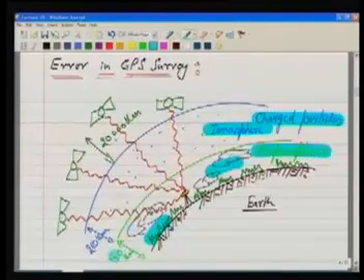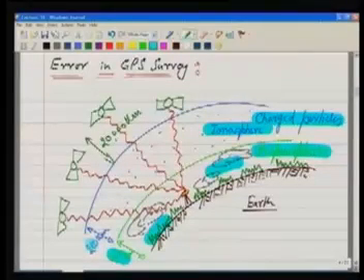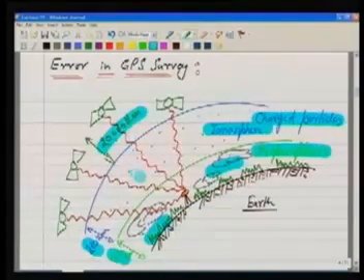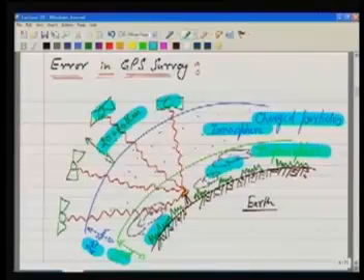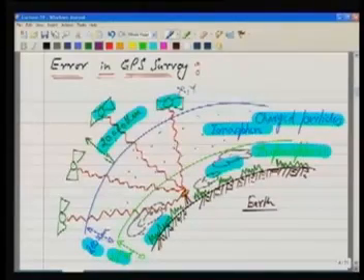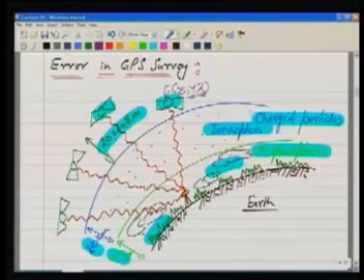Now, this is the height or the width of these spheres. At 20,000 kilometers above the ionosphere, we have our GPS satellites. Well, let us follow the movement of signal, or where are the sources of error? Because we are making use of these positions X, Y, Z, means where the satellite is. We need to know this position correctly. If there is problem in knowing this position, it will affect the coordinate which we are going to compute.